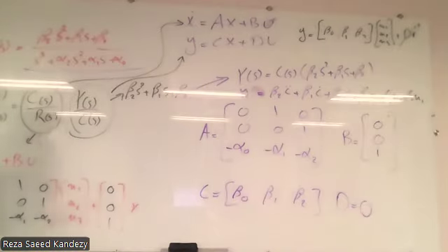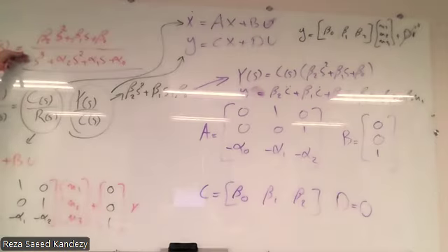So if you have such a transfer function, only by looking at it, you can find out what A, B, C, D are and find the state space model in less than a minute. To be honest, this is a very normal system transfer function. It happens a lot when you define the system and want to design or analyze the system.